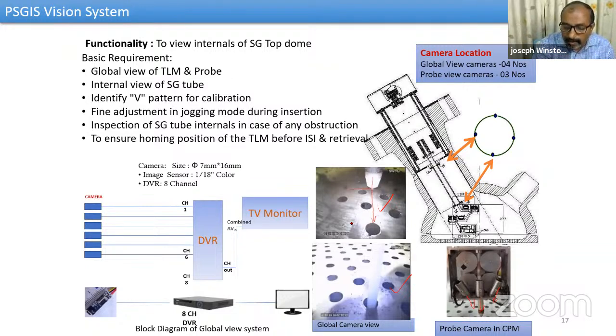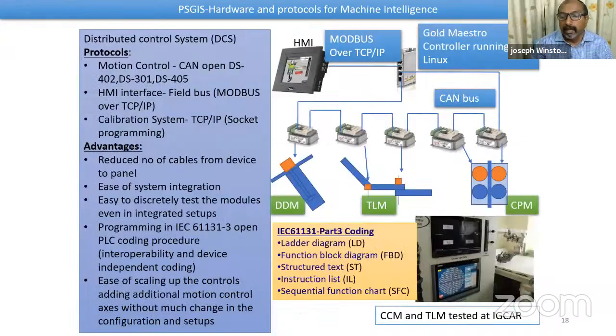Normally, we keep a clearance so that it doesn't interfere with the tube sheet during the movement of the robotic arm while positioning to different tubes. Then we push the cable and the probe down through the holes, tubes which will run 23 meters down from this point of insertion. And some of the controls you can see here, as I told you, the deployment module has a motor here.